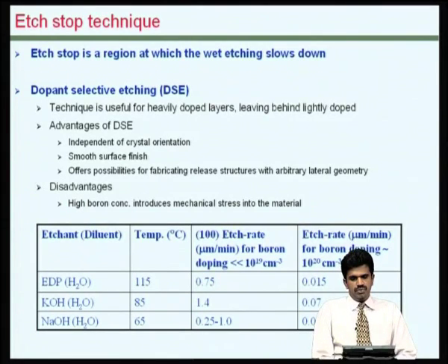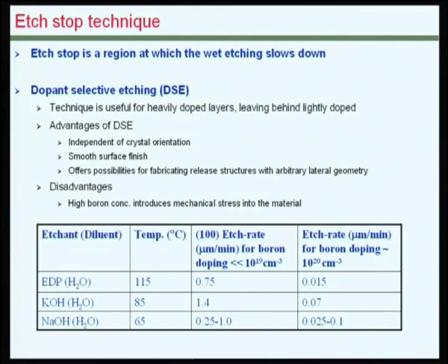It is difficult to time the etch process so that you dig through this 500 micron of silicon, if you are using a standard diameter substrate wafer, and finish the process to leave a 5 or 10 micron thick diaphragm. Hence, alternate ways of stopping the etch process are required in these cases.